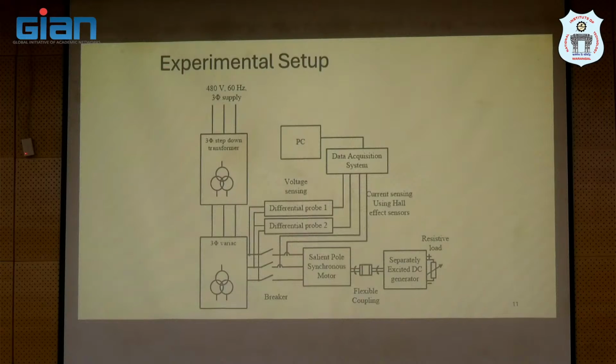You would have collected data and you will see that there is a zero line or just a straight line. So what I'm trying to say is you need to really inspect the raw data as you collect, and only then can you conclude whether it is good enough or not. You still need this expert knowledge to check whether you have a sinusoidal looking wave, and three-phase waves that are equally spaced. One of the common mistakes I made while I collected data was that the current probes are direction sensitive.